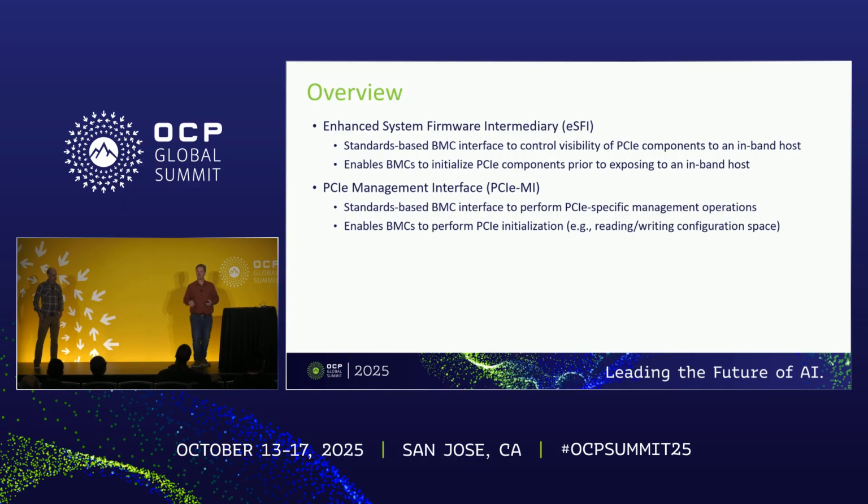Drilling in a little more, what eSFI gives you is external management entity control over the PCIe links and behavior on the links, and a lot of associated things you would need related to that. PCIe MI then is a set of commands focused on managing those control points and really just managing config space, so both config space read and write.